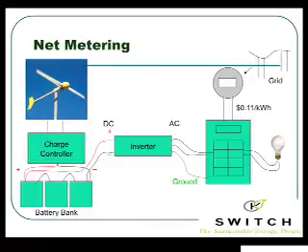So how it works with wind, it's basically you have the power coming in from the turbine, and this can be in DC. And this can go down into your battery bank if you have that and charge up your batteries. And the next thing from that is you can pull this DC current from your batteries into the inverter. These little boxes are things that you'll need to talk to your installer about. And basically it changes that DC into AC.